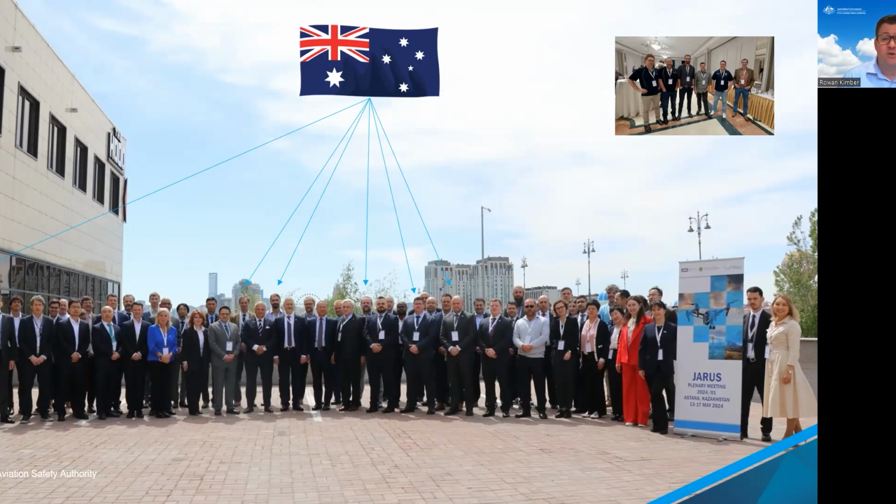Our application of SORA is also not entirely consistent with other nations. Whilst we follow the model, there have historically been key differences in the way we approach the criteria. One classic example is the way in which we approach the M1 ground risk mitigator, as far as Australian operators do at least. Where we see in European nations, an initial area is carved out from any higher population density, and so the initial ground risk is based on a lower population.